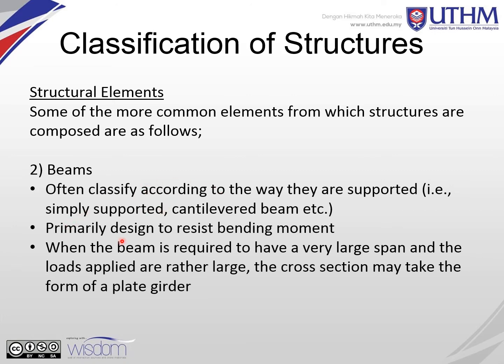Beams are primarily designed to resist bending moments. For a beam, you will calculate the load on top, either UDL, point load, and so on, and the moment, and then you will calculate the shear force and bending moment. You will get the maximum value of shear force and bending moment. So it is designed to resist the bending moment on top of it.